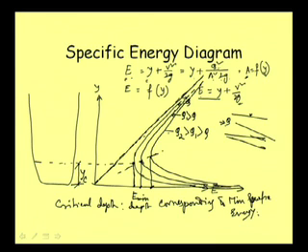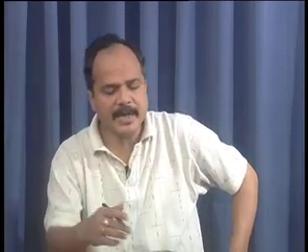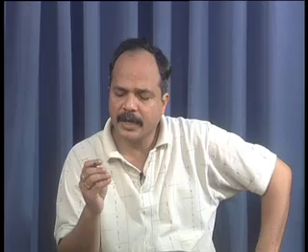All these things we are talking about are for a particular channel section, because when we say area is a function of y, definitely if our channel section changes, that function will also change. So the same equation will not hold good, and the same shape will not be obtained. So for a given section and a given discharge, we get a relation which gives us a minimum specific energy, and that minimum specific energy corresponds to a particular depth, which we call the critical depth.